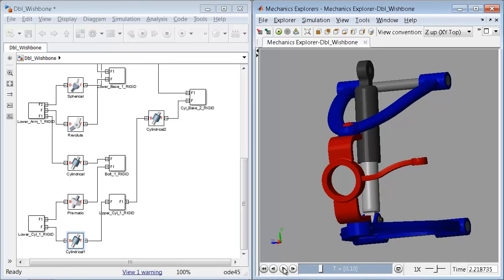The installation of SimMechanics Link is pretty straightforward. You just download it from our website and install it. Again, it's an add-on to MATLAB and it's free of charge. The only thing is that you have to register it with your CAD platform. Step-by-step instruction to all that can be found on our website, or just by typing doc space smlink to your MATLAB command window.